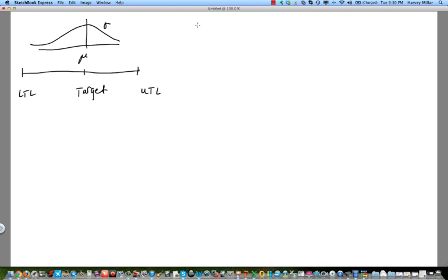So usually we'll have the target plus or minus a tolerance. Example, 5 plus or minus 2 centimeters means that we're willing to accept between 3 to 7 centimeters, right? If we add and subtract those two things. So what happens is that we sometimes want to know whether or not our process is capable. Well, if it so happens that the range of the process is within the tolerance limits, then we're cool. Then chances of producing defects are relatively small.